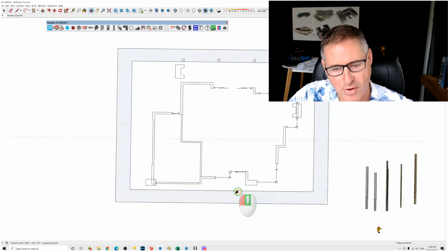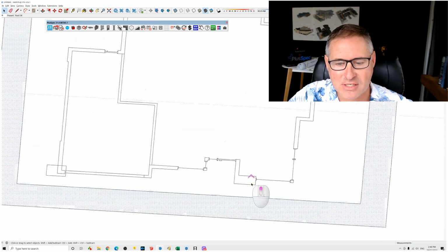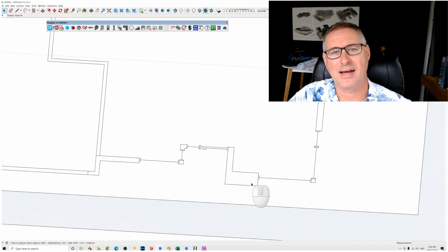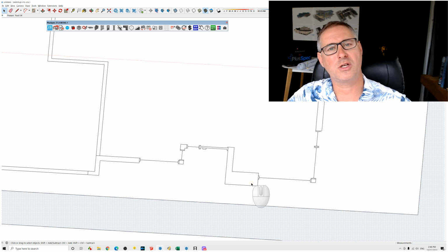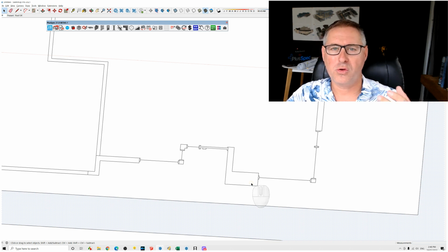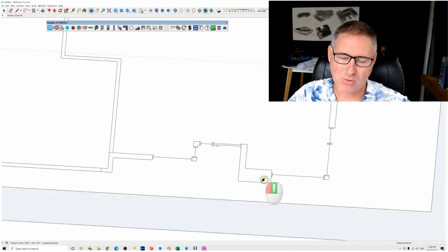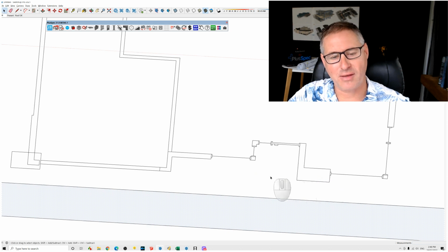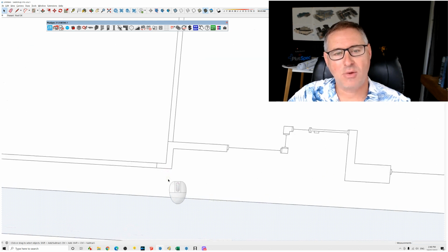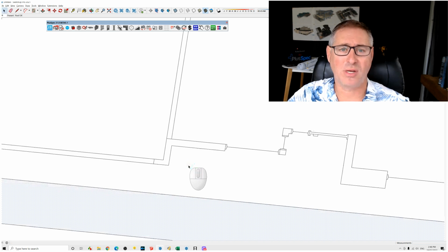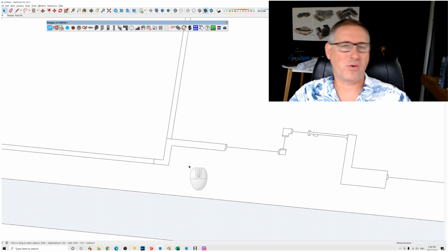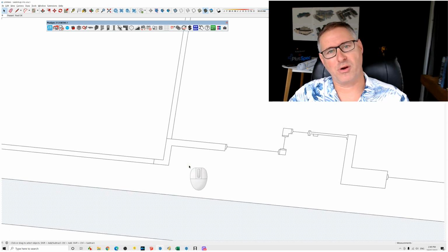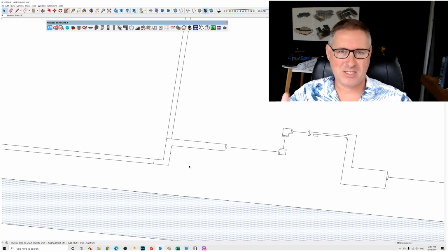So the remedy to it is that instead of designing from the outside wall, at least consider what type of wall you could potentially use. Now I'm not saying actually no, because you know what, that takes a little bit of thought. However, if you just understand roughly what size that wall is, and this was explained to me this morning, the architect said, well, I know if I create an 11-inch wall, when I actually build the project, if I use option A, B or C construction method, it's still going to fit.